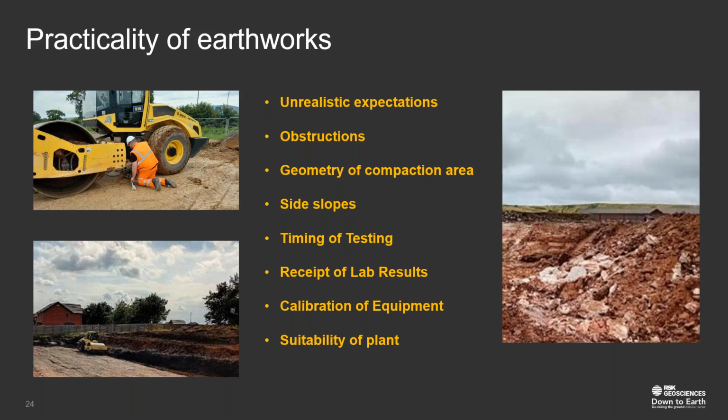which costs quite a good deal of money, or you're going to have to settle for a lower degree of compaction and perhaps some other solution to your foundation problem, perhaps piling or deep trench foundations through the fill and then compact it to a lower standard. So sometimes, yes, you can struggle to make a silk purse out of a sow's ear.